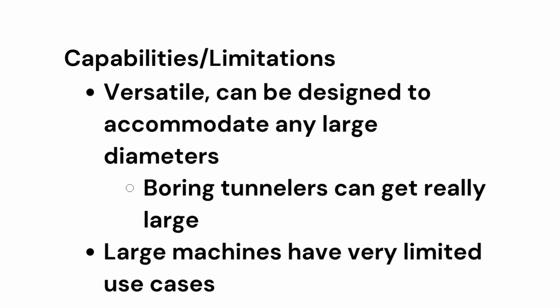However, large boring machines have very limited use cases and often exist to be used one time. Smaller diameter, mass producible jobs are also better accomplished using a vertical turret lathe instead of a boring machine.